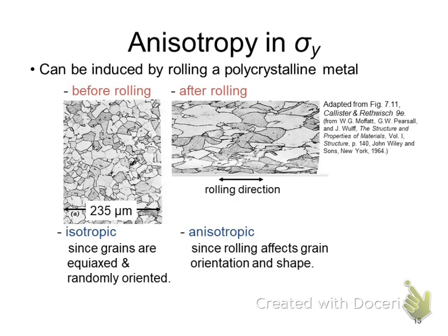So let's look at a concept first called anisotropy or anisotropic behavior in crystalline materials. We can induce this by squeezing a metal plate thin. Before you roll, and we call it rolling, which is moving that plate through a series of rollers and squeezing it together. Before doing that, you'll notice that our crystals are reasonably the same size. They're reasonably similar shape as well. They're random and they're all approximately the same dimensions. This is what we're going to call isotropic.